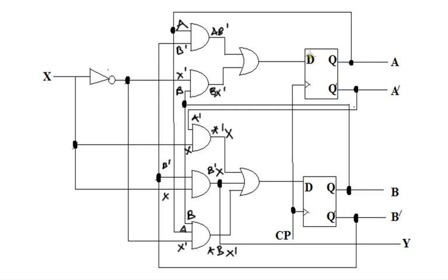And we should remember that for a D flip-flop, the next state equation Q of T plus 1 is always equal to D. That is, whatever is our D is our next output. Now, the first thing I will do is to determine what are the inputs to this first level of gates, and from there we get their output to serve as input to this OR gate, and finally determine what our Ds are. How do I do that? I will say, okay, this point, if you look at it, let me follow it. It is from A, so I'll put A here. And the same line extends to this gate, so I'll put A here also.